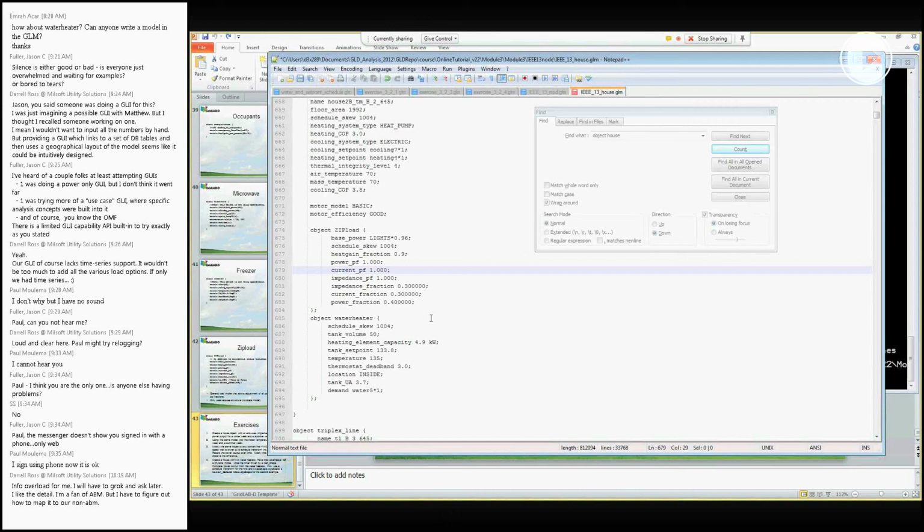You can basically capture the overall effects by just a non-thermostatic load in the zip loads. So basically this says, if I lower the voltage, then I'm going to lower my power, but I still get effectively the same amount of work out of it. So this is a lot of your things like your computers, your TVs, and those type of things. Whereas your water heater and your HVAC system are much more of a closed-loop system. So if you lower or increase the voltage, then you change the way they actually interact with the environment, and those effects are captured in there.